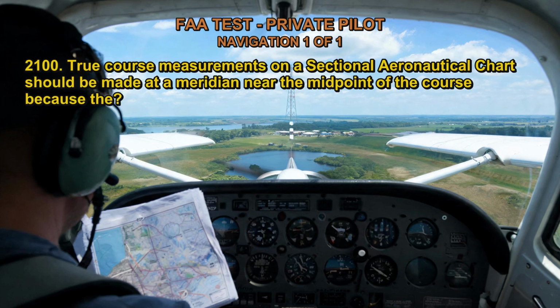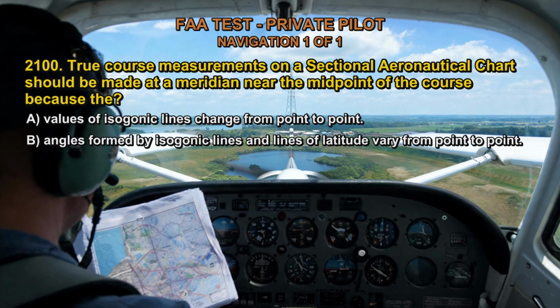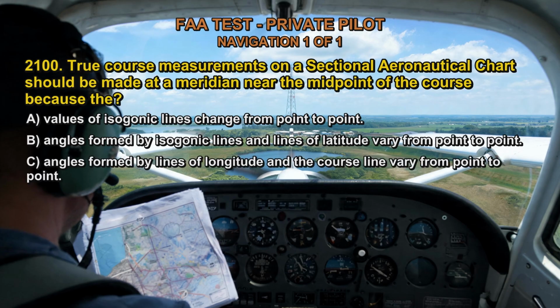2100. True course measurements on a sectional aeronautical chart should be made at a meridian near the midpoint of the course because the a. Values of isogonic lines change from point to point. b. Angles formed by isogonic lines and lines of latitude vary from point to point. c. Angles formed by lines of longitude and the course line vary from point to point.